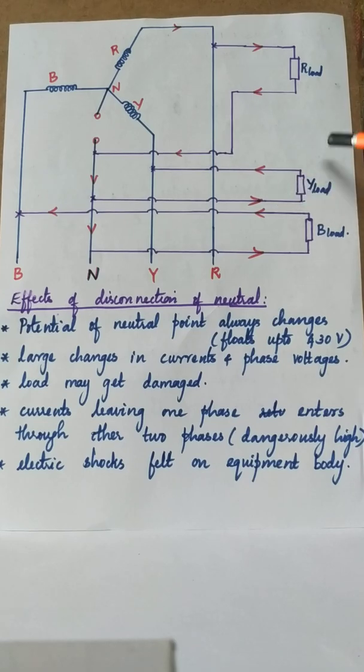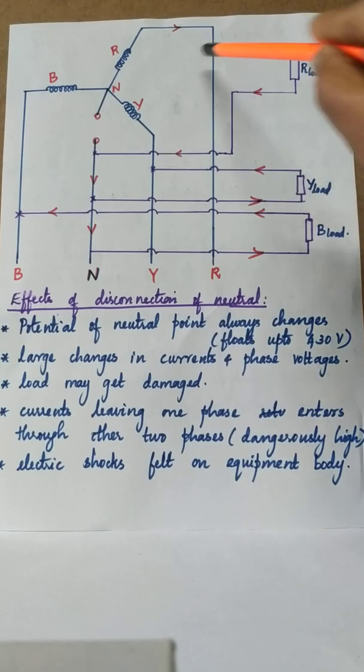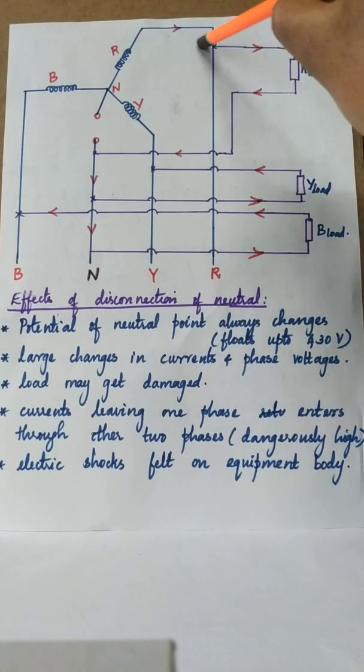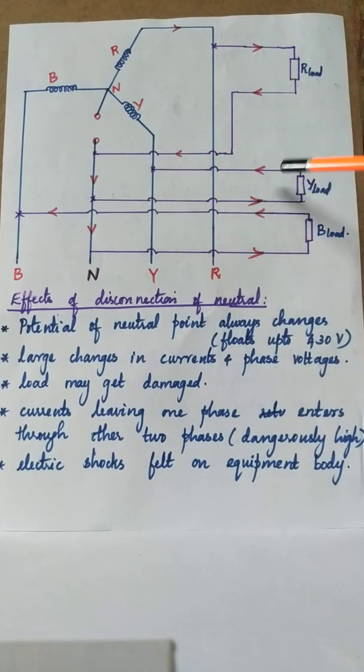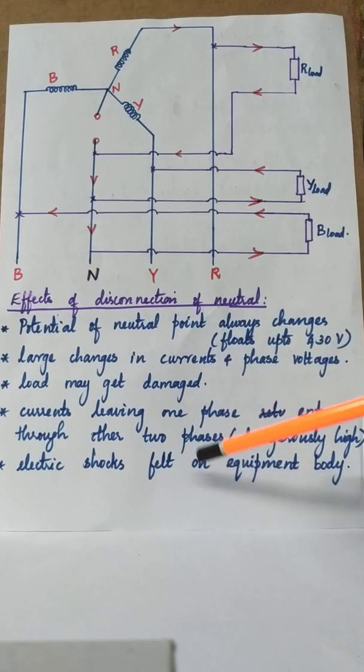What will lead to the overcurrent? The current which is leaving one phase will enter through the other two phases, so dangerously high currents. In this situation, sometimes it may lead to electric shock if we touch the equipment case.